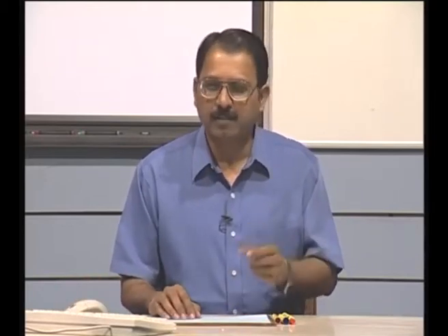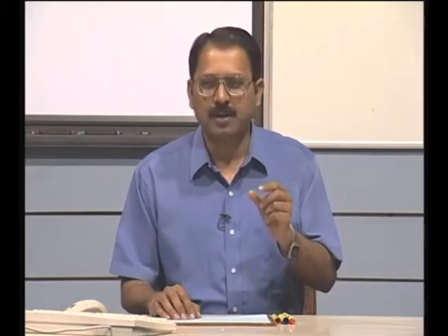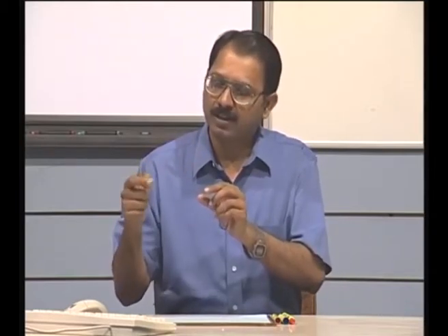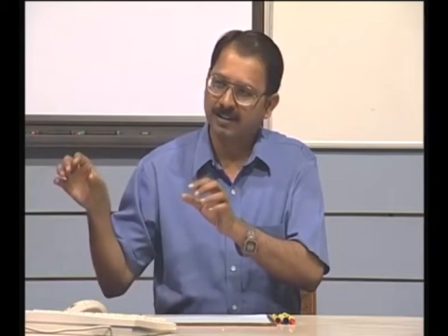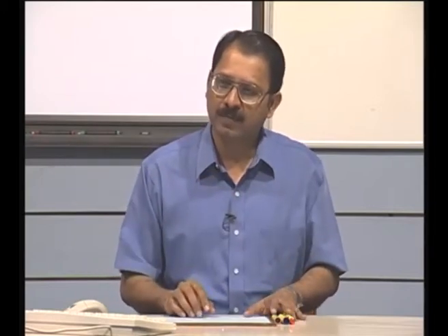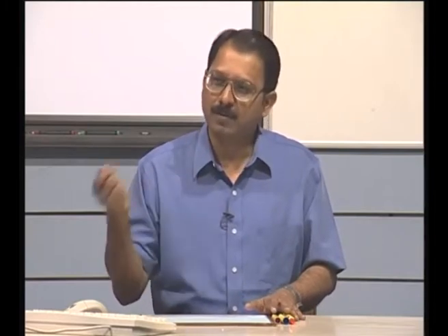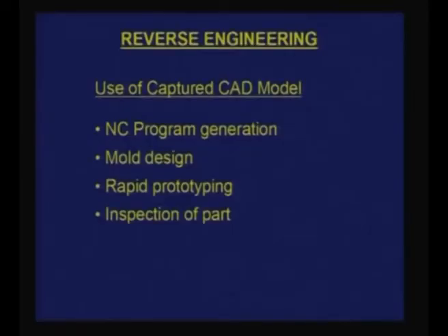like in fact there are many situations where a plastic part has been worn out. This has been reverse engineered. After reverse engineering, you have the geometry which is the worn out geometry, but you are able to correct it to get the intended geometry, and I can just want one more part in a process like rapid prototyping and just replace this part with the existing part.